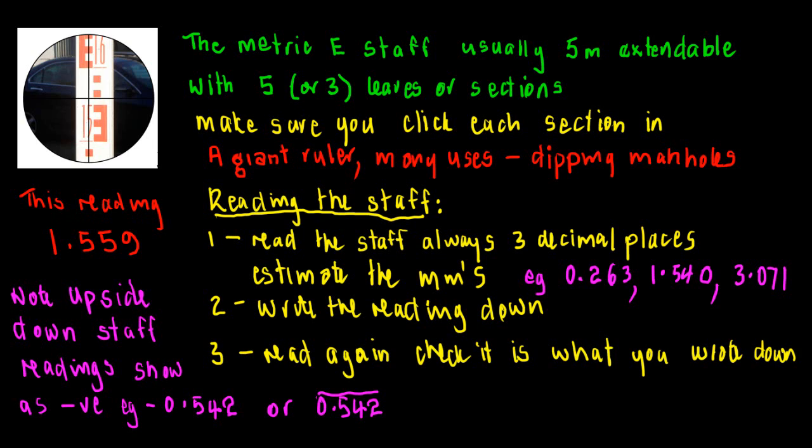The general rule is that if you're going to come anywhere closer than 4 meters of a wire, you need to take extra care and possibly have people in place as spotters and experts in place that know how to deal with those wires. One of the ways of dealing with the overhead hazard is to actually remove some of the sections from the staff so that it's physically not possible to extend the staff the full 5 meters.